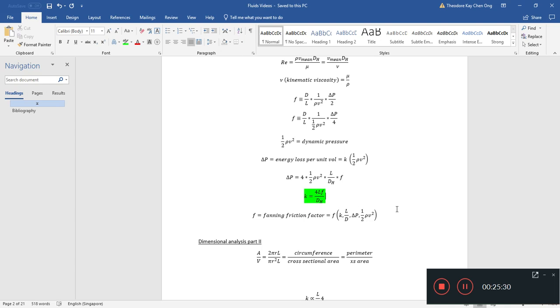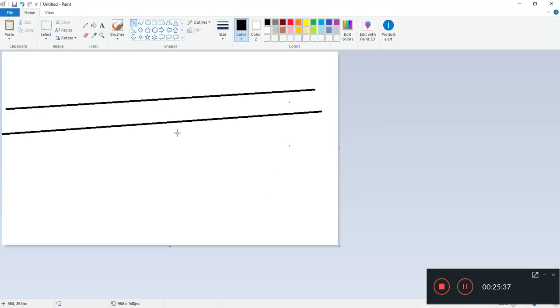Once we find out what our K value is, and we have our fluid properties, for this 1,000-mile long pipe we can start to design pumps, because now we can estimate the energy loss in the pipe. We can design pumps that make up for this energy loss. You can design one pump here, one pump here.